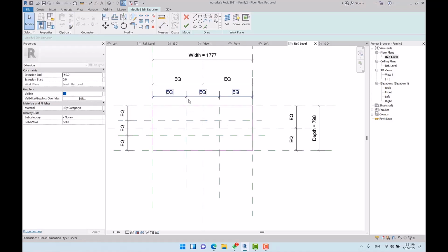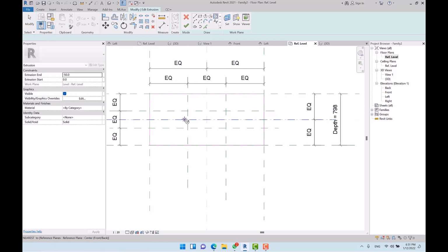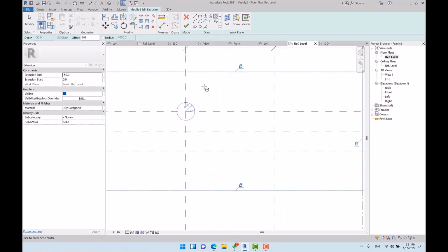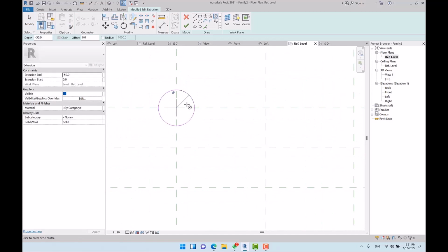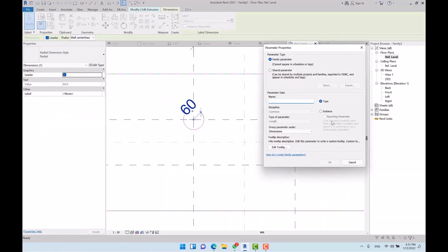Here we can delete the dimensions and then associate the parameters only to 1/3 part of the geometry, so that we can control the size of the void, for example, or the opening, by making the geometry parametric. So for creating an opening, I pick circle and I sketch it right here. I want to associate a parameter to the size of the radius. I name it, for example, hole R or hole radius.